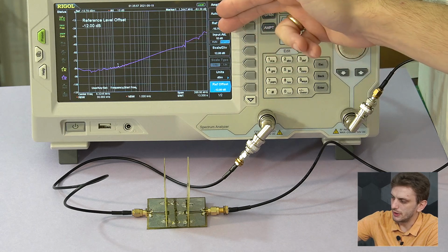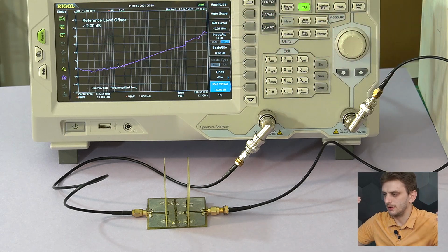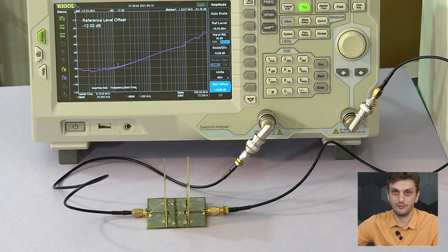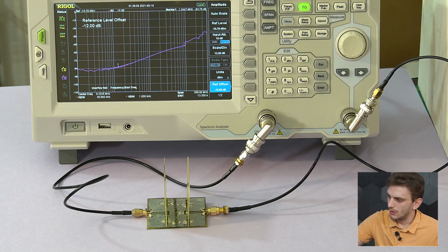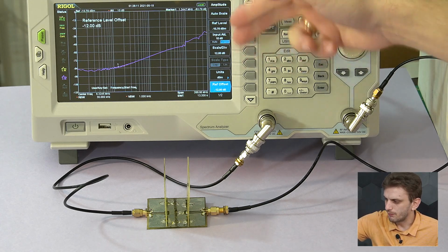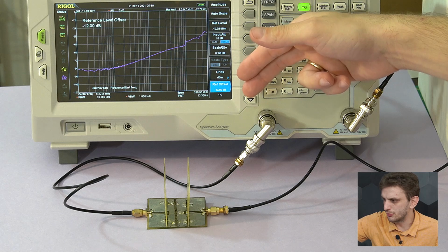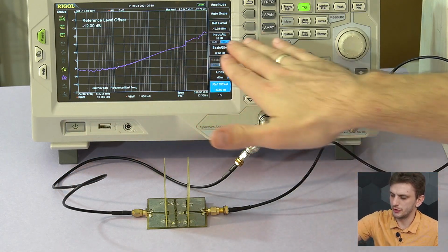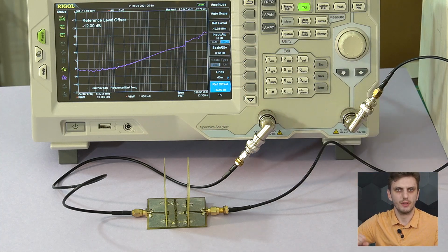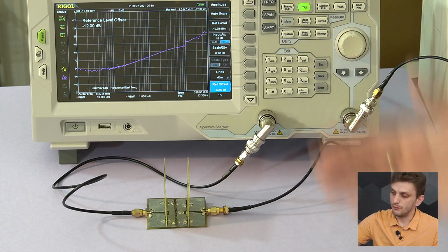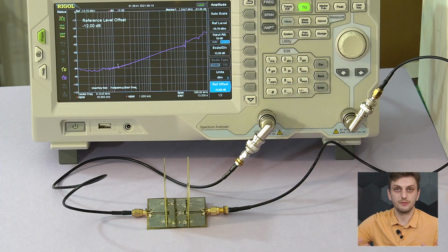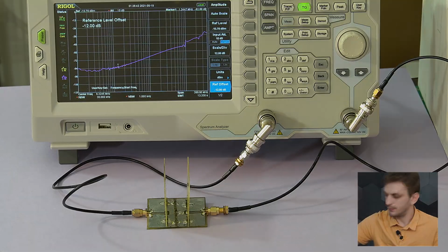Now I have a bit of wiggle here in the measurement, and this is mainly because of my impedance mismatches, so this thing is not a 50 ohm system, but for today's measurement this will be good. So one more thing to point out here, the measurement is performed from 100 kHz up to 400 MHz. So above 100 MHz we start to have some issues, but it's okay. But anyway, we can see our electric fields coupling. So our system will be good enough to try out our experiments on.